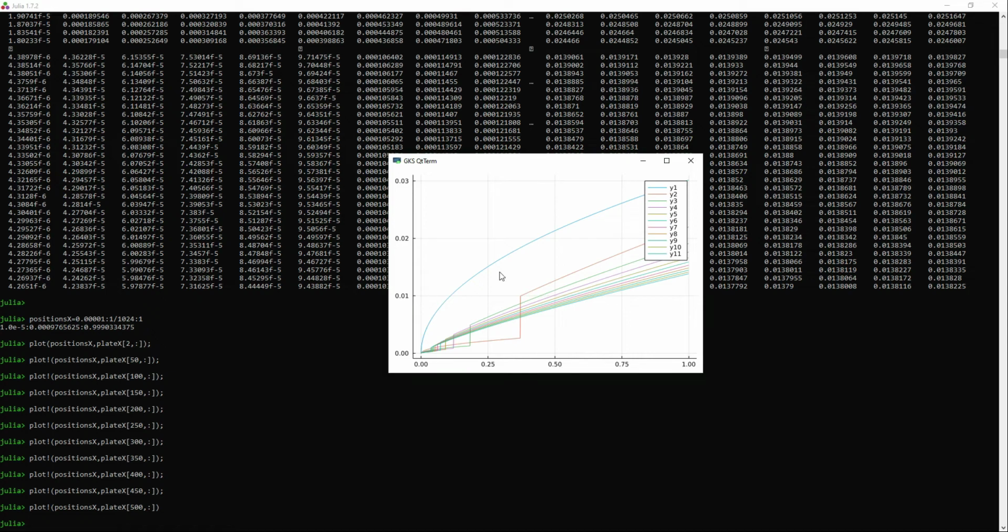When we start accelerating, you see how the boundary layer is smaller, and you can see how we have a jump in the thickness at the points where we transition. And again, since we don't have a model of the transition, we can see this odd looking jump. But as you can see, the faster our flow goes, the smaller the laminar boundary layer becomes.